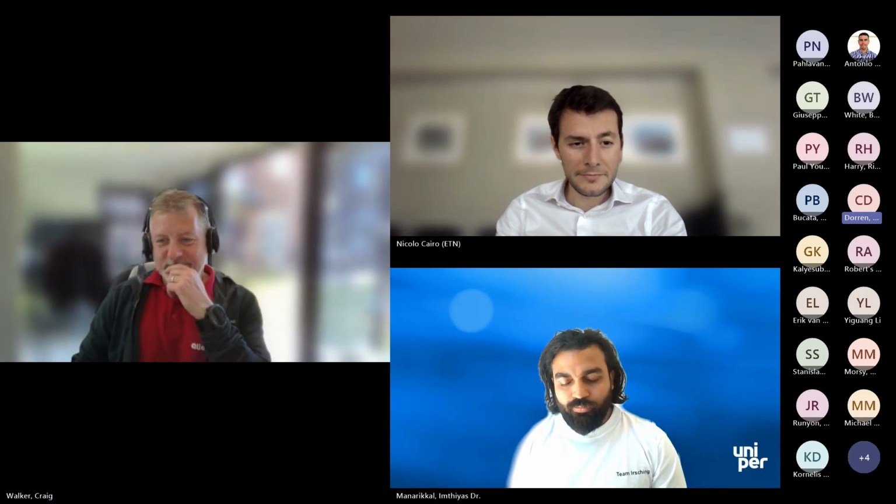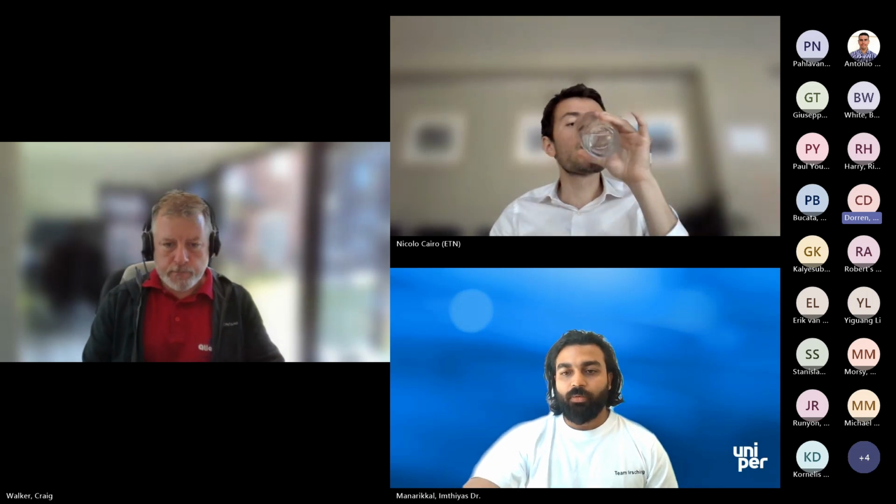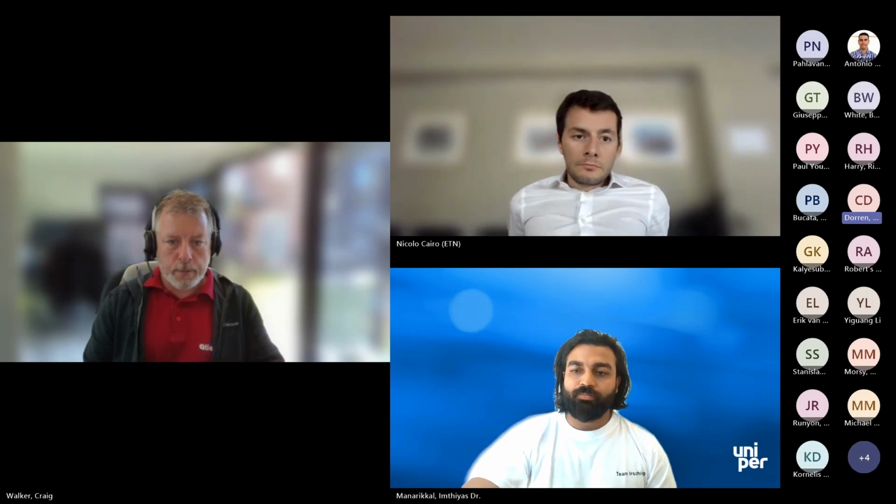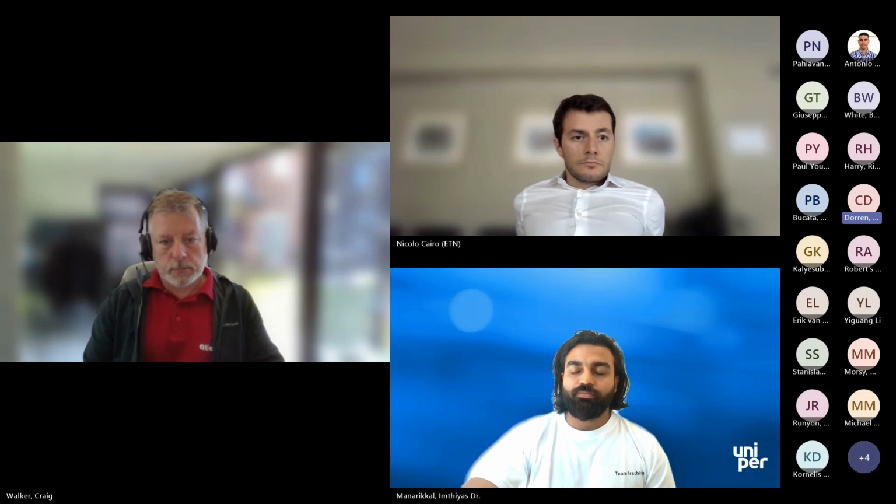So just to give a background, the PI data that we collect from our systems is also used in models to look at performance of the plant. So it's looking at pressures, temperatures, flows, etc., to look at what a standard plant runs like. And then if it notices any differences, it can highlight it in advance that we're having changes in conditions that the site can then act upon. So it's a little bit more than just vibration and thermo. There's some additional data that we use that we have modeled on our sites to look at performance and how that can change based on pressures, temperatures, and the rest of it.